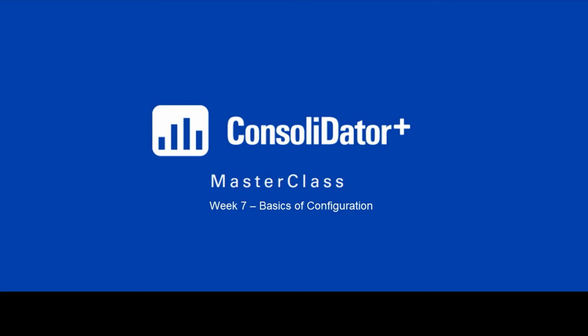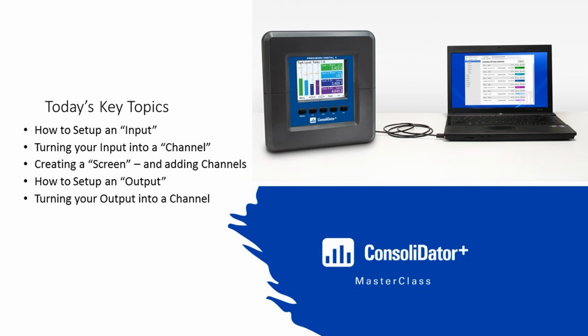So specifically, what we're going to look over today is how to set up an input. That's like a 4 to 20, a physical process input. We're going to learn how to turn that input into a channel. And then we're going to learn how to create a screen and then add those channels. And then lastly, we're going to look at how to set up an output and then tie that to a channel that we've created.